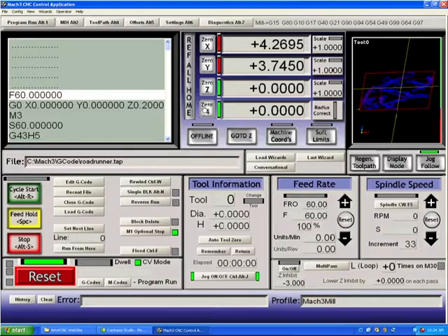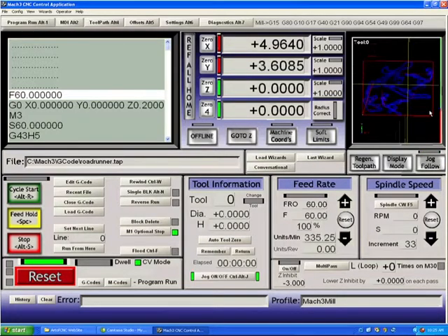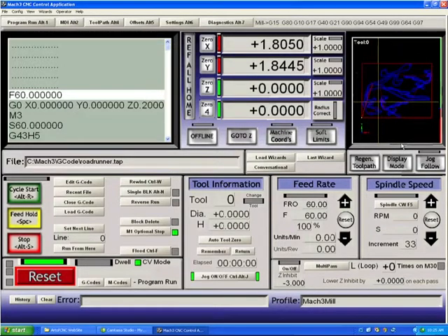Now, whenever you zero DROs, these are the DROs, by the way, digital readouts, these two yellow lines show the X and the Y axes intersecting. So at this moment, my tool is centered somewhere up around this roadrunner's foot. If I jog my axis, you can see that the drawing moves to show where the tool is currently at when I'm in jog follow mode. If I turn off jog follow mode, the lines move to show you where you would be. Again, double-clicking will reset the system.